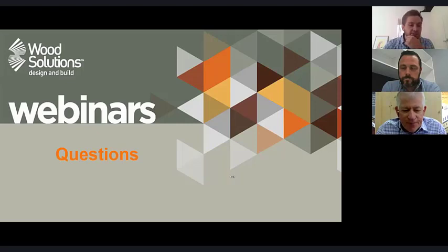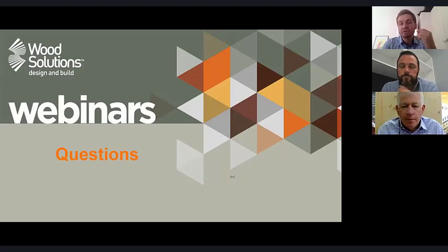Yeah, that ties back to, I think, Jerry Howard's question about brick panel facade systems. So typically that sort of panelised or curtain wall facade approach, you'll have tolerance built into some form of transom. Most of them are top hung on the level above, really. So that's where you have to work with the facade supplier to add adequate tolerance to account for these sorts of axial shortening issues.